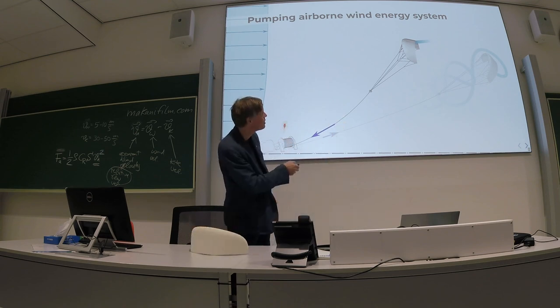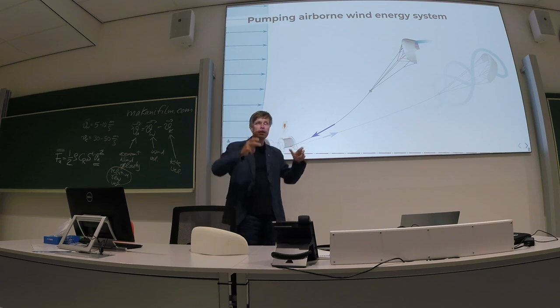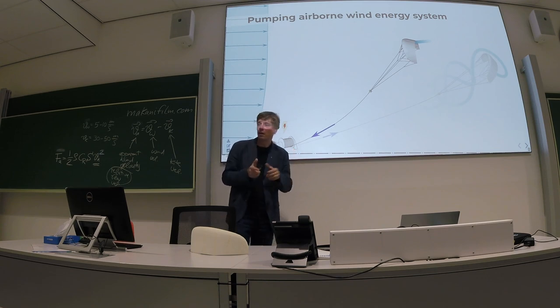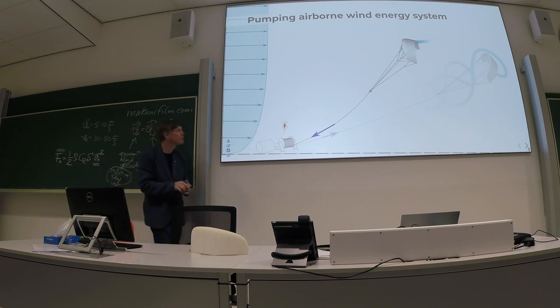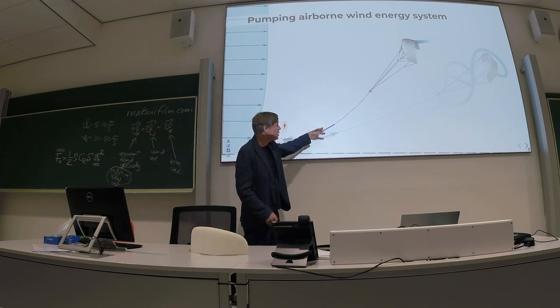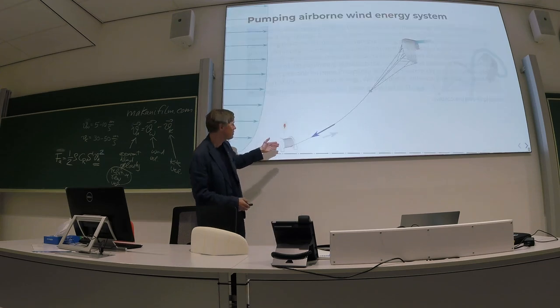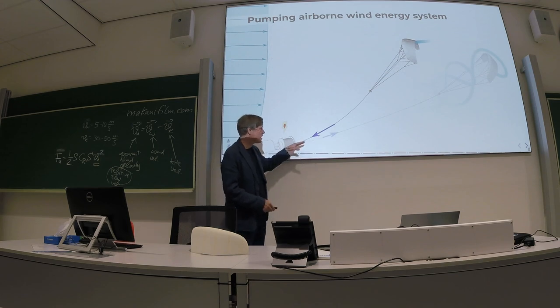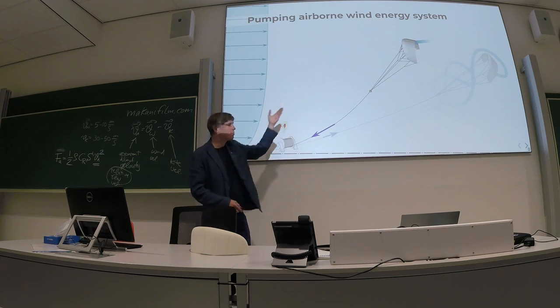And you see this here a bit illustrated. When you pitch down a wing, you decrease the angle of attack. And decreasing the angle of attack will vary this coefficient here, this aerodynamic resultant coefficient. So the force here is lower than during reel out. And because I have a higher force during reel out than during reel in, we have a net energy over such a pumping cycle.